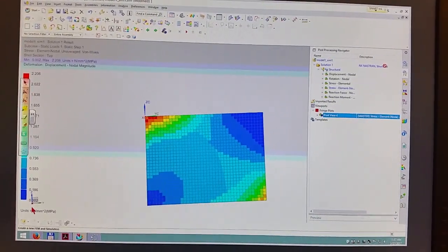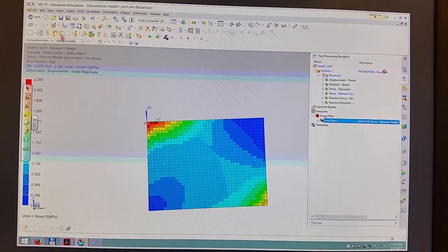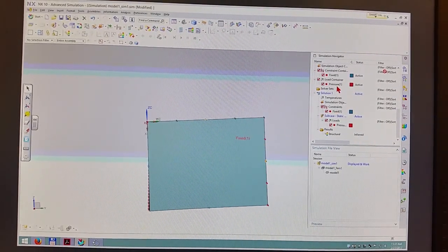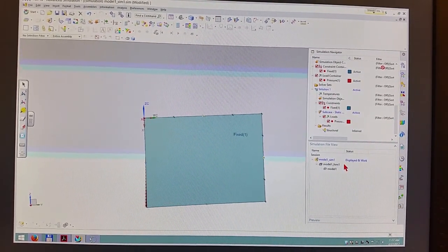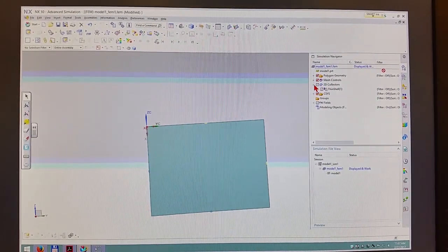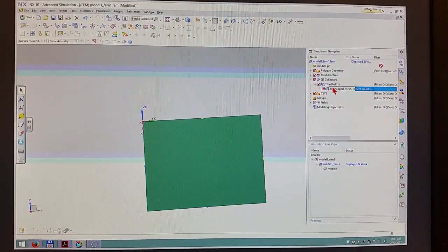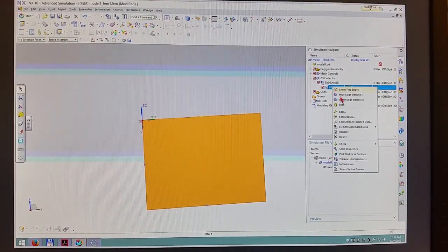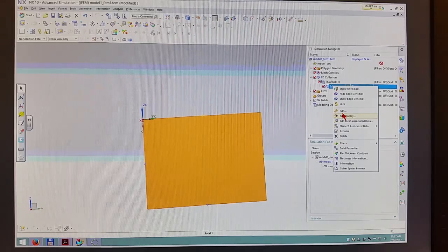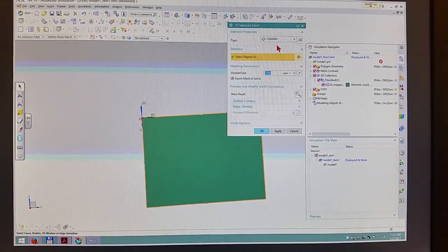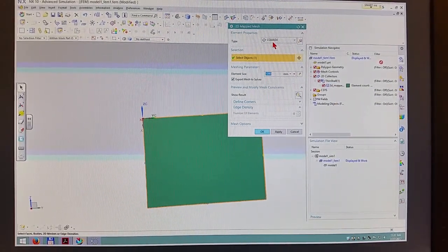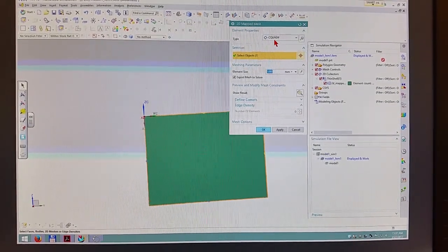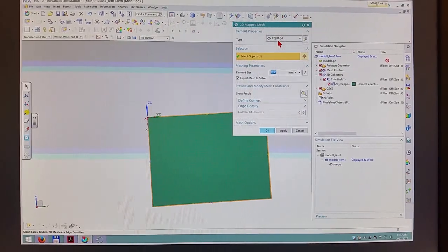So it's still not nice and smooth. If I come over here, return to my model, I'm going to click here, and go to my FEM. Here's where I did my map meshing. I'm going to go ahead and edit this. If I look, I used quad 4, right? I used linear. That's not that great. There's no reason why you should be using linear in this class. You will lose points.